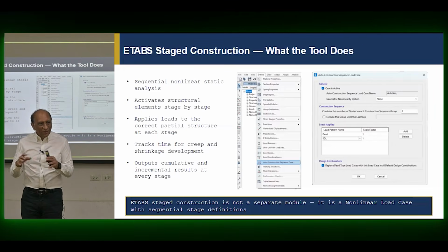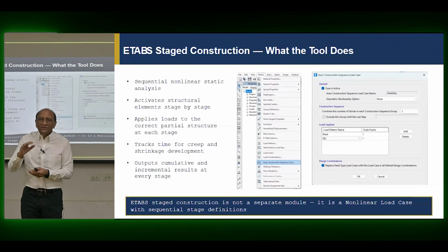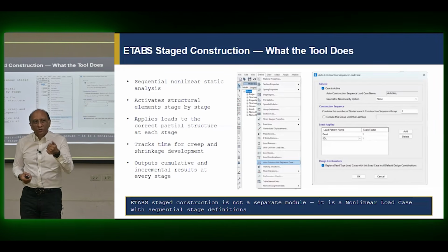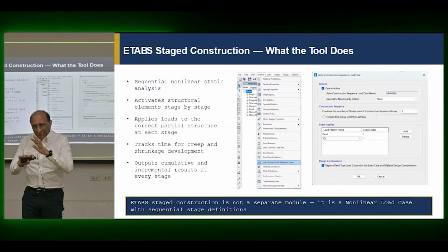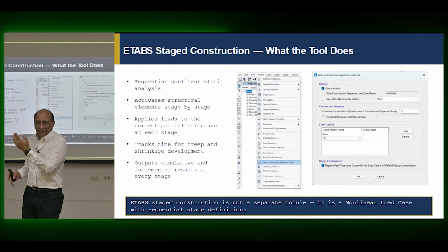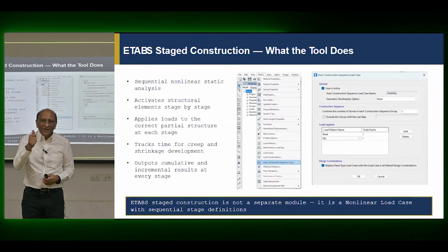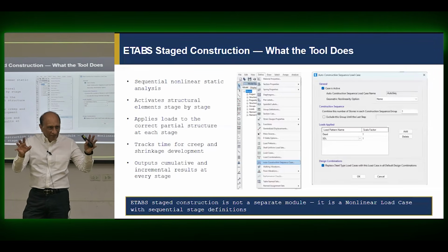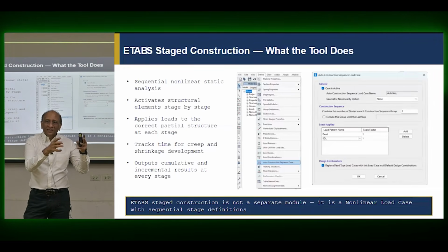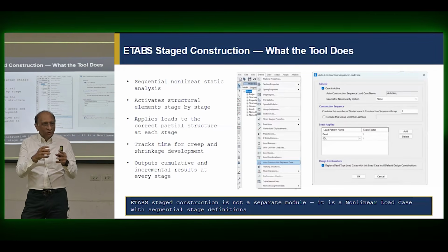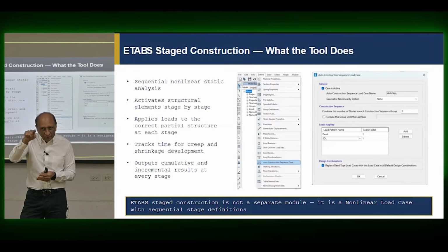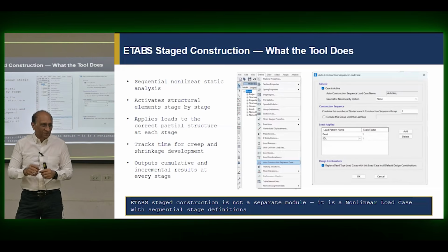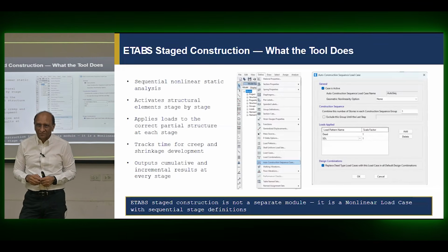So which means that you have to understand. To create a construction sequence, you have 4 or 5 tools in your hand. Remember the basics. Everything else is detailed. Number 1, you can add a structural group. You can create a group of your structure elements, beams, columns, walls, whatever, any group. And then you can say, this is my group number 1. And then you can say, construction sequence, step number 1, add group 1. So that is called add structure.